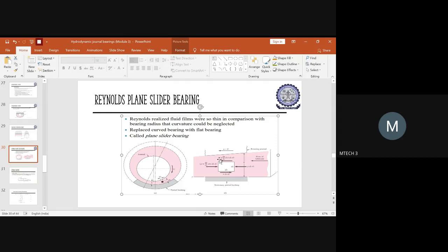And due to this, a shear stress will be generated across the surface where the journal is rotating. And hence you have to add here the shear stress value, how the shear stress is varying with respect to your y-axis. And again you have to write down dx into dz. So this also will be in the direction in which the flow of lubricant is. So this is what you have to understand.